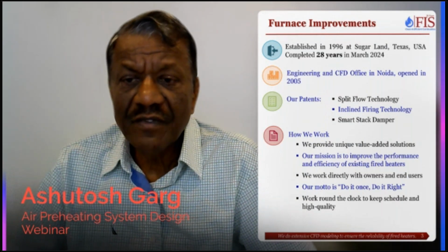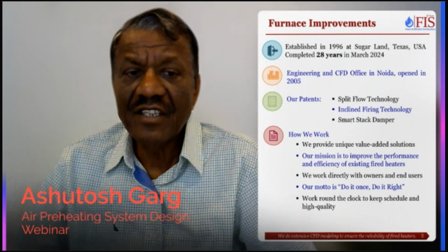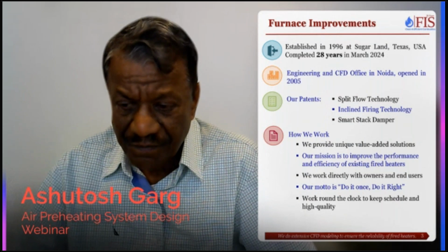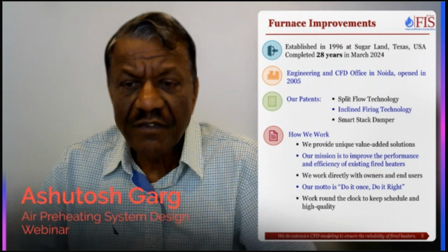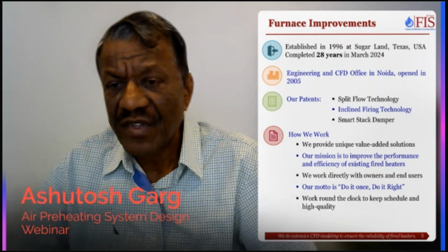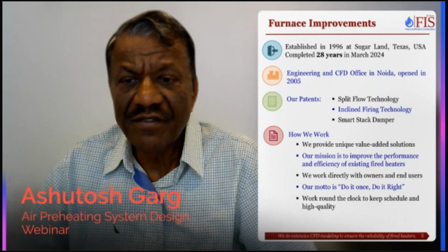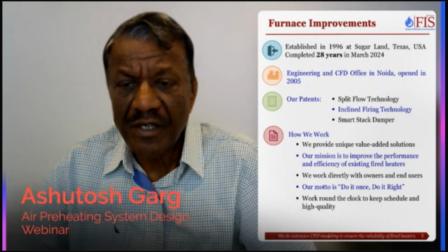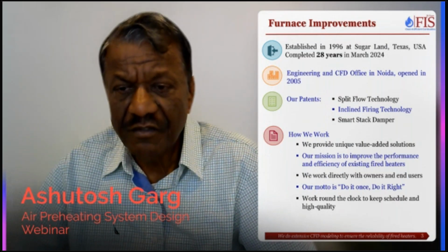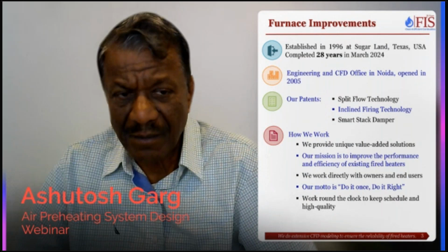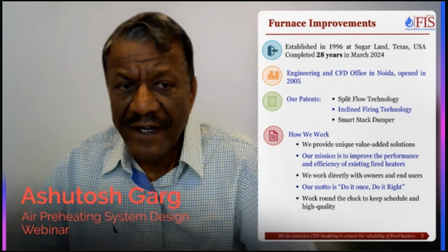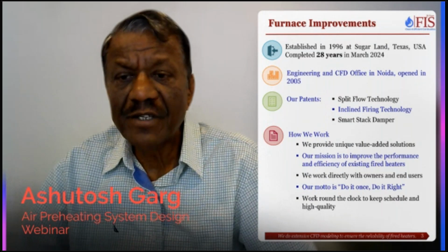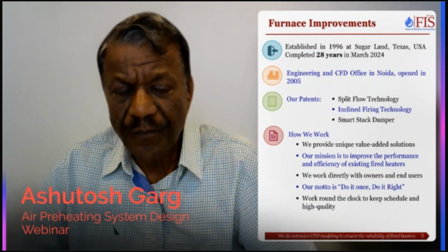And out of that questioning came 3 patents. The first one was split flow technology. We have about 12 references of split flow, mostly in the catalytic reformer or platformer service, even though we have used it now in other applications. And it's a very good technology for increasing capacity, reducing pressure drop across heaters.